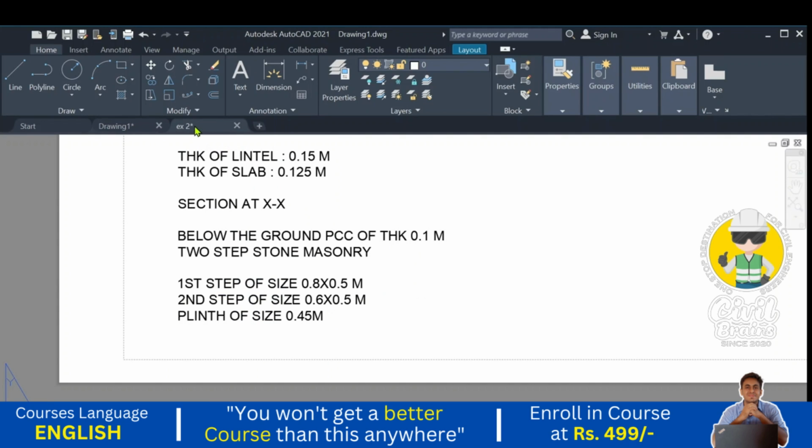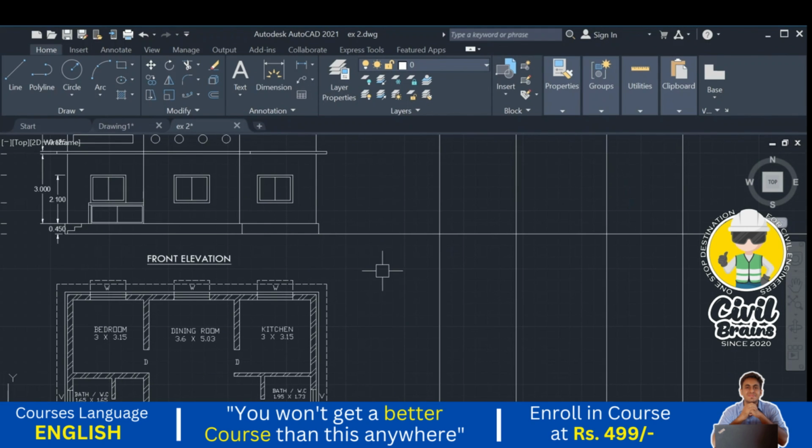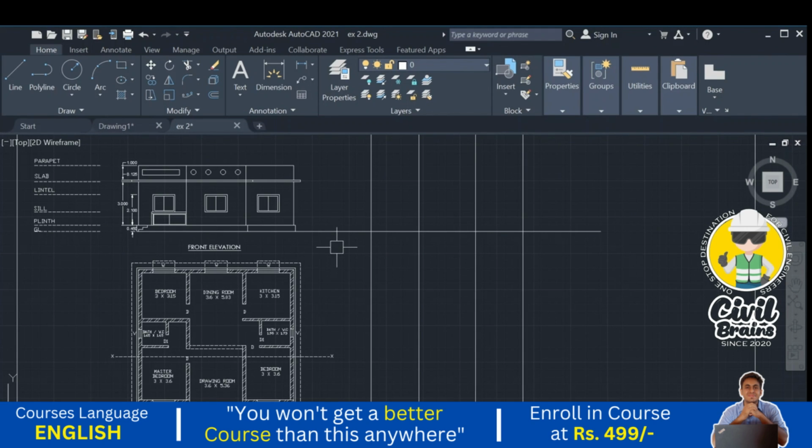But as per the engineering, how to identify the depth of the foundation? To identify the depth of the foundation depends upon the soil bearing capacity of the soil. What is the SBC of the soil? Depending upon that, how much load will be transferred to the soil. Depending upon that, we need to go for the excavation, or depth of the foundation.